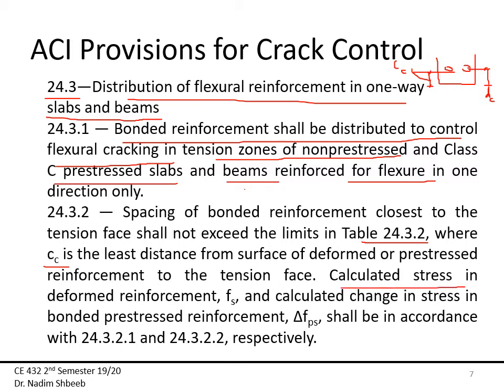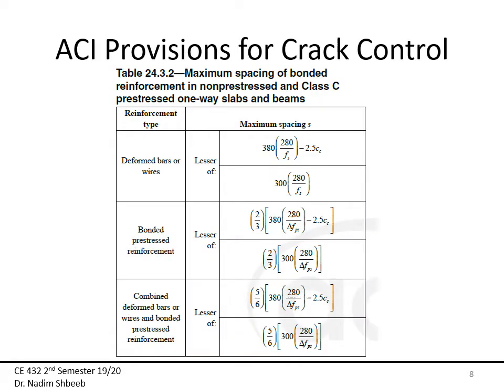The calculated stress in deformed reinforcement fs shall be in accordance with sections 24.3.2.1 and 24.3.2.2 respectively. For us, we are only concerned again with reinforced concrete, not prestressed, so we will be concentrating on this section right here. Now, the table that we're talking about: my maximum spacing, s, should be the lesser of this equation right here and this equation right here.